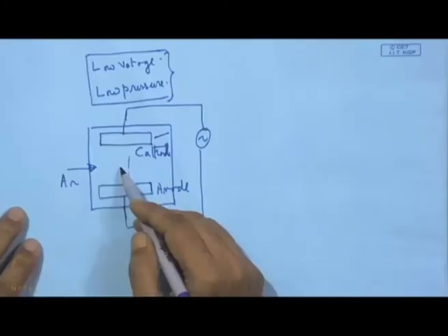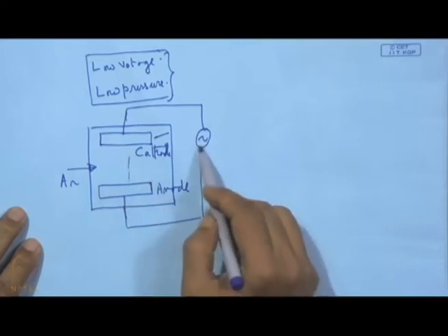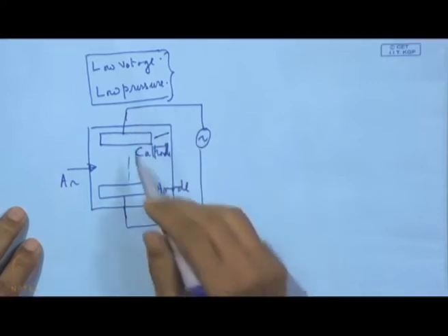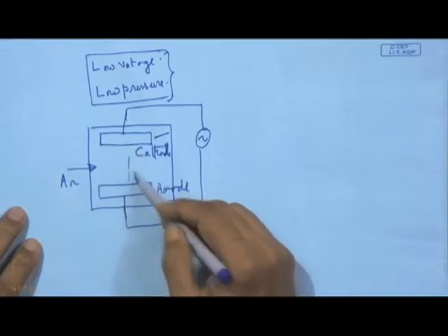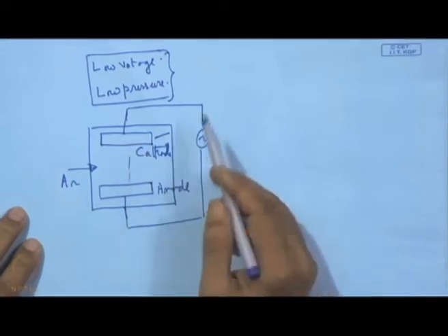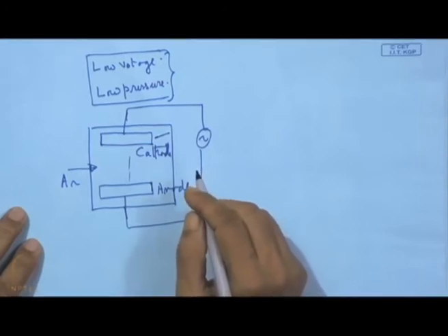So, one can immediately understand the efficiency or utilization is augmented and improved a lot just by providing this oscillating motion to this electron, and that is possible just by giving this alternating voltage across these two electrodes which are put inside this sputtering chamber.